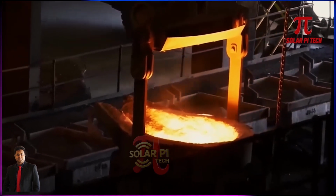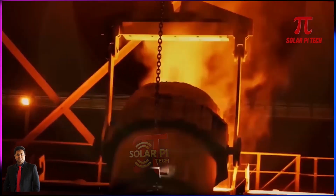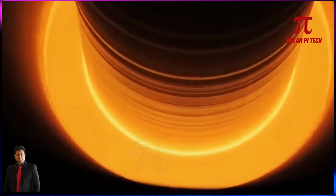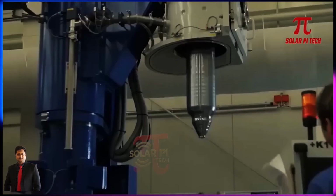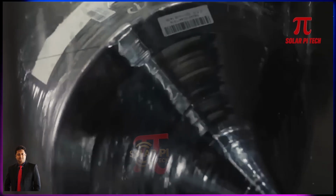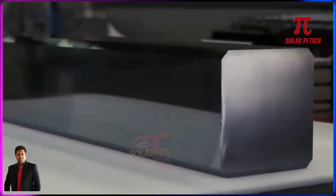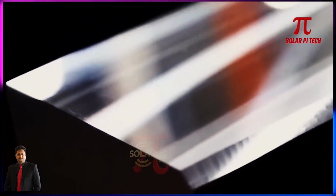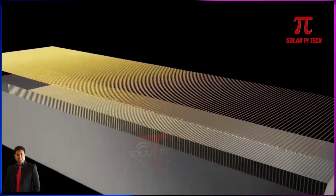The purified silicon is melted and formed into ingots, which serve as the raw material for solar wafers. These ingots are produced using either the Czochralski process or the float zone method. In the Czochralski process, a seed crystal is dipped into molten silicon and slowly withdrawn to create a cylindrical ingot. This block would be far too big to put on your roof, which is where solar panels usually go. The average roof wouldn't support it, so now it needs to be cut down to size.